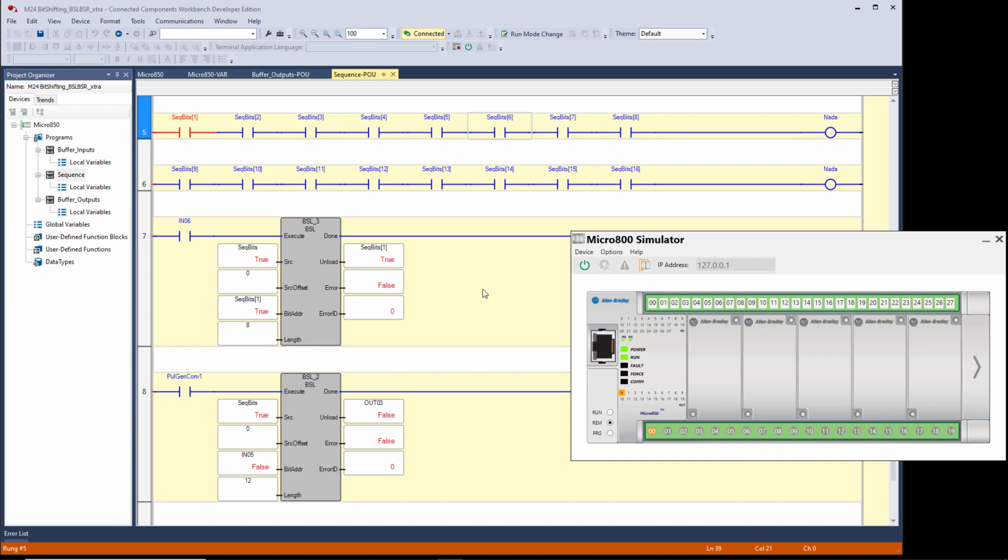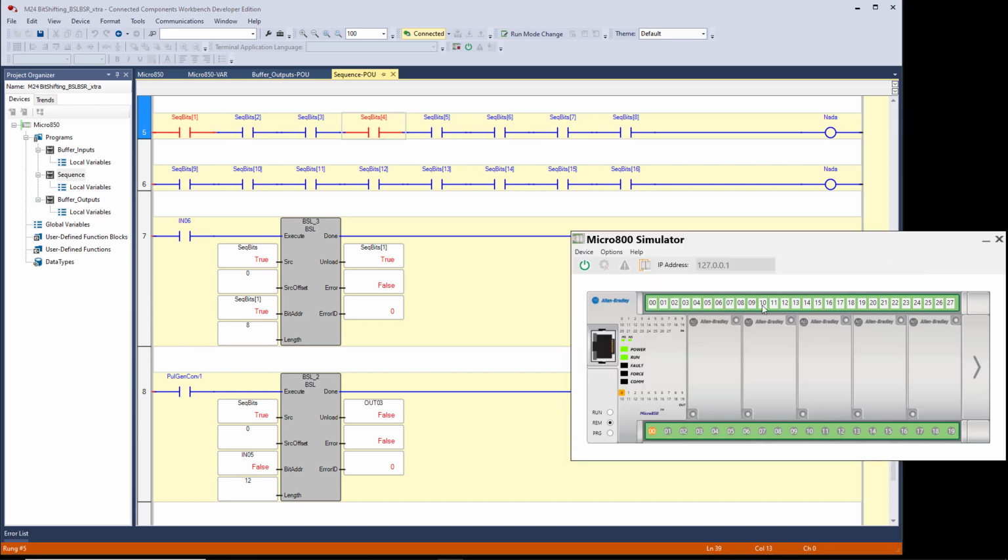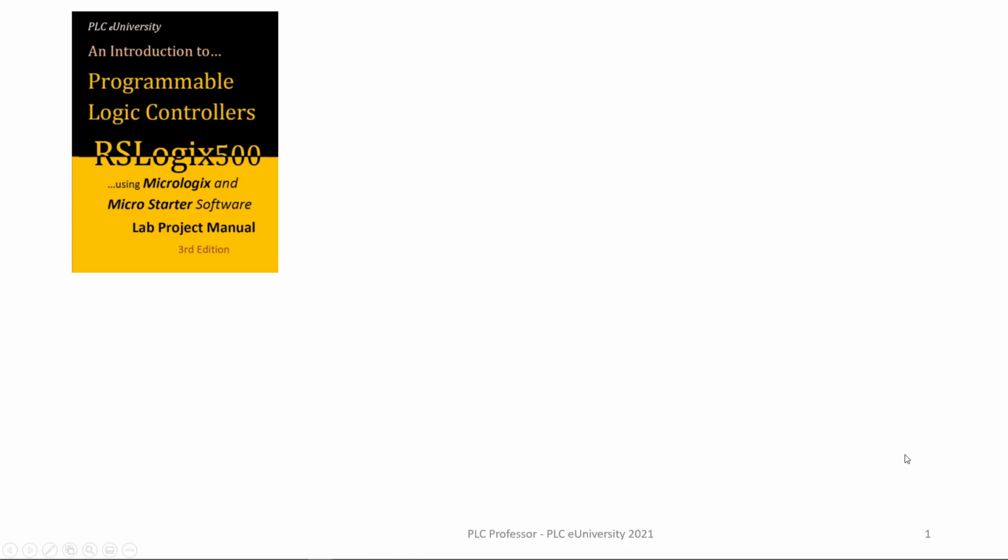So if you had a rotary index table with 8 stations and you did a certain function or procedure at station 4, when that logic is complete, then it would turn on that bit. And then when you rotate the table, that part now moves from 4 to 5 and so forth. Now you can do this with bit shift right. So we could set up a bit shift right. So if you reverse the direction of the rotary index table, it would reverse the direction of the recirculating bits.